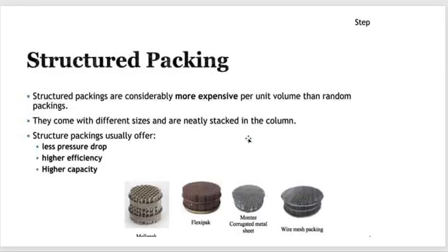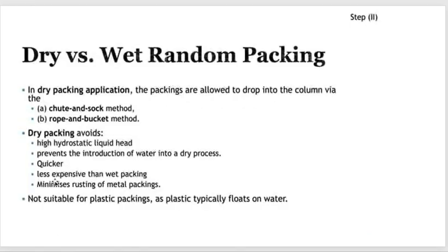The structured packing here, there are types of structured packing. This structured packing usually offers less pressure drop, high efficiency and high capacity. So we recommend it a little bit if you are targeting the higher capacity, the higher efficiency, the pressure drop, effective contacting time, you need to work with structured packing. This is more recommended.